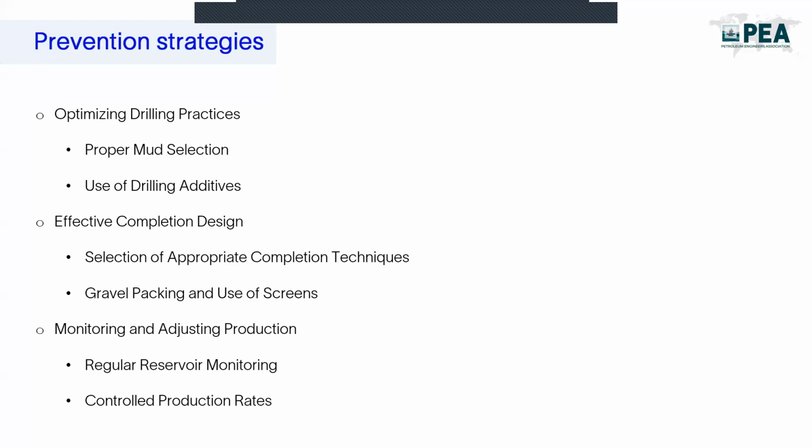The solution is to use low filtrate muds to reduce the invasion of the drilling fluids into the formation, which can block pore spaces and reduce permeability.